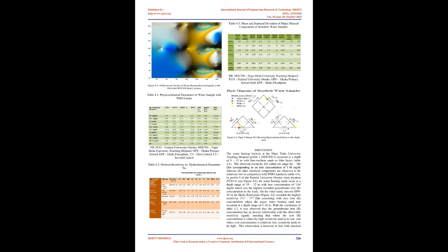Guided by aquifer depth information derived from the geoelectrical data interpretations, 6 boreholes were proposed, 2 in each of the 3 locations. While drilling, lithology logs were generated at 3 m interval, and water samples collected at the reach of major aquifers. The water samples were immediately labeled with masking tape and taken to the laboratory for physicochemical analysis within 12 hours from the time of collection. 6 samples in all, comprising 5 borehole samples and 1 bottled water which served as control, were analyzed.